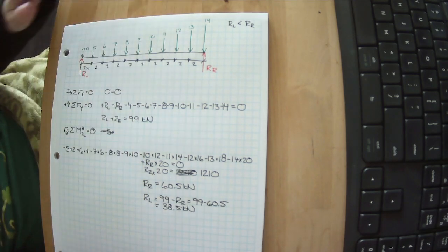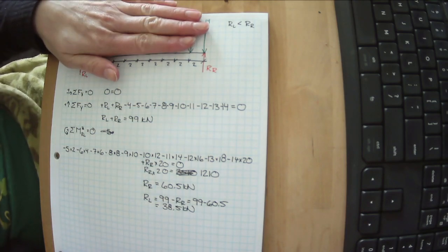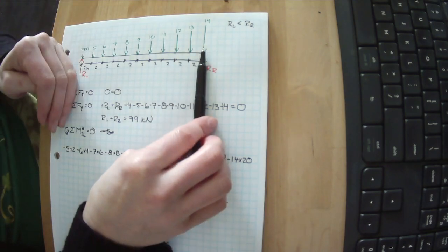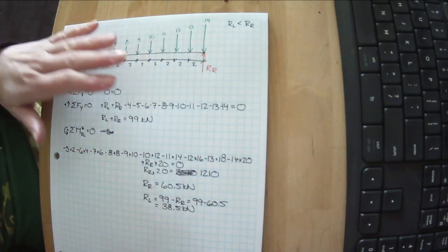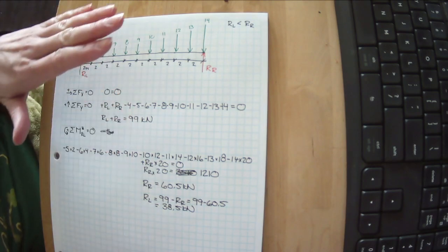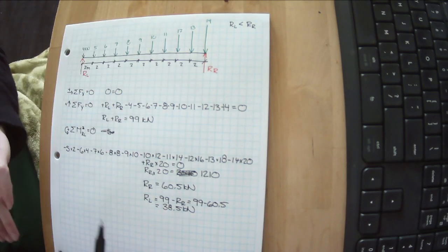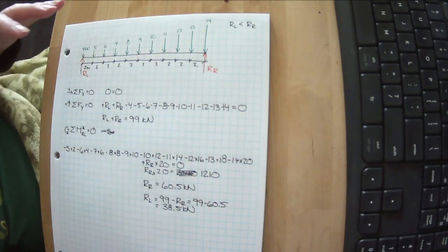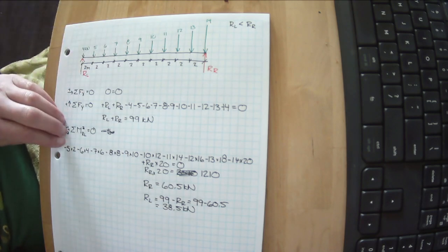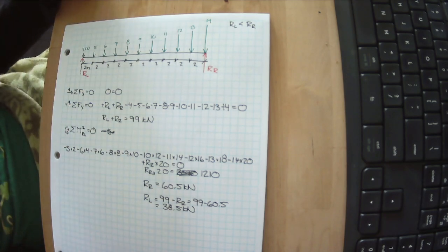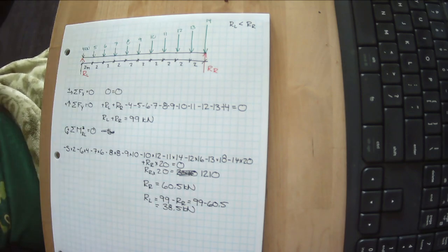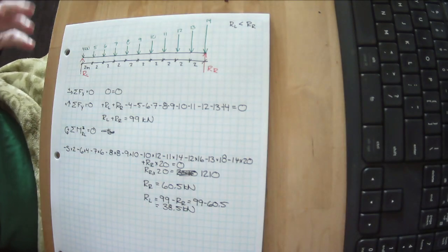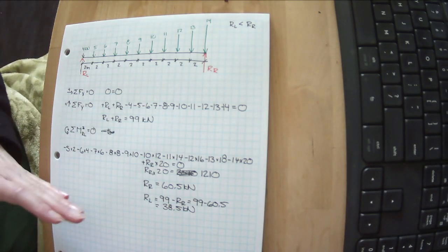So now, if you can determine the loads on a beam, you can figure out what the reactions are that support that, or what is required to stop this beam from moving. And if it's moving, we don't have a stable structure. So to be stable, we need the sum of all of these equations to be 0. So now we have a method to find reactions. And this is huge. Now all of a sudden we can start to move the loads through our building.